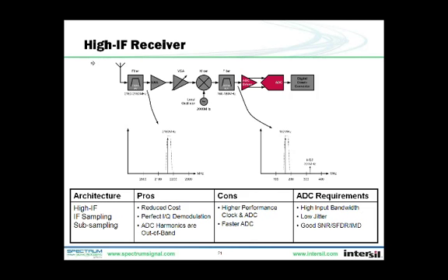This architecture does require a higher input bandwidth at the ADC, but this is generally not a problem for today's converters. So this architecture provides a good compromise for software-defined radio. Compared to direct conversion, the higher ADC input frequency followed by a digital quadrature demodulator offers improved performance, while omitting the second mixer from the superhet reduces the amount of fixed analog circuitry.